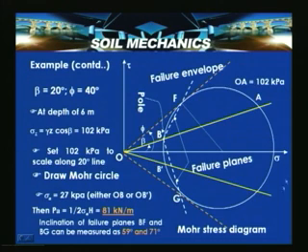Once we draw the Mohr circle, sigma A is equal to 27 kilopascals, which is nothing but either OB or OB dash, both are the same. So, we get the active earth pressure ordinate, 27 kilopascals. Then Pa, the active earth pressure thrust, is equal to half sigma A, which is the base, times H, which yields about 81 kilonewton per meter.